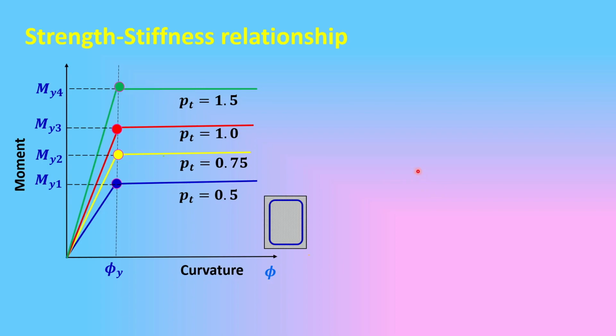So this we want to verify further and understand what is going on inside. The previous diagram we have drawn here in a different scale. So I have this blue curve for the percentage steel 0.5%. My section is this, which is not changing. The percentage steel is changing. I have not shown it here because it will be changing gradually.